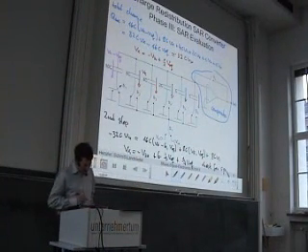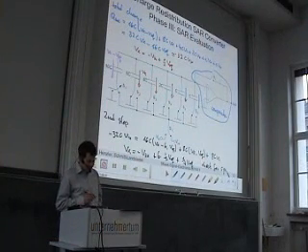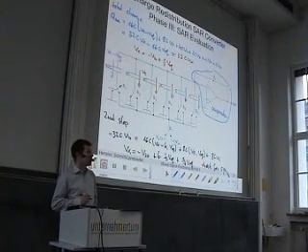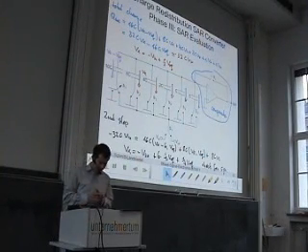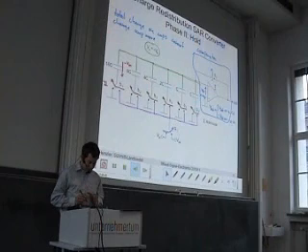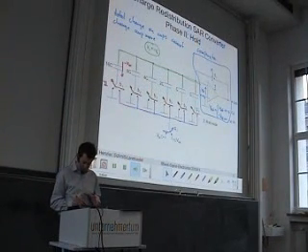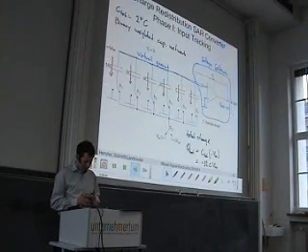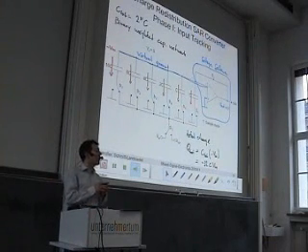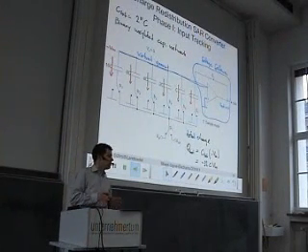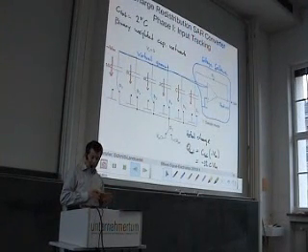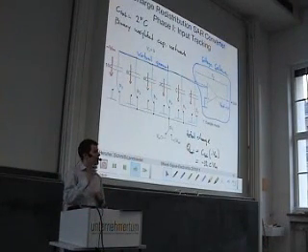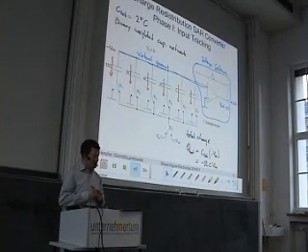Yeah, it is transferred from one to the other because there is a different voltage drop. If you look at this condition here, the voltage across all caps is the same. Okay, so the charge on each cap is given by C times this input voltage.